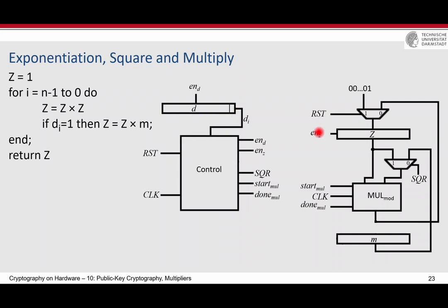If you do it very carefully, you can save some time with respect to storing the register and shifting this guy, then the overhead is lower. But this will not be very, very fast, because anyway, bit by bit, you need to check for the square and multiplication. At the same time, you need to wait till the modular multiplication module actually did its job.